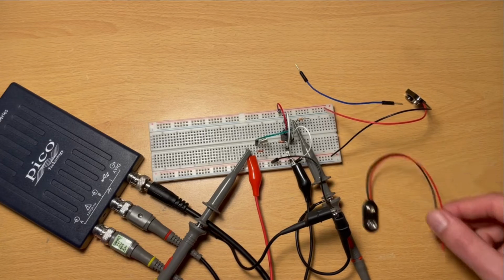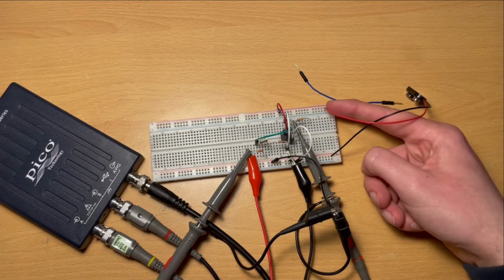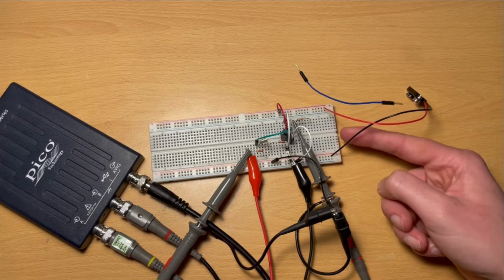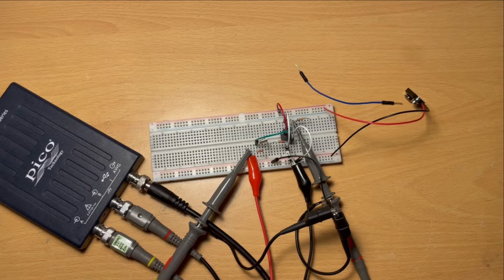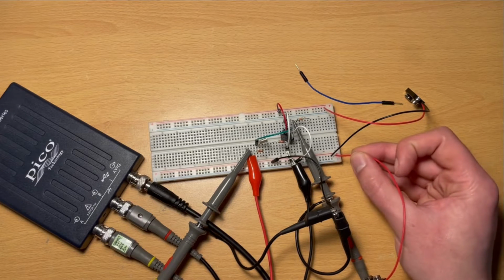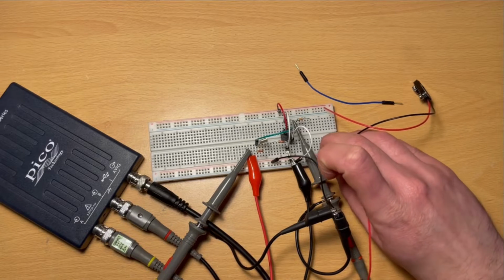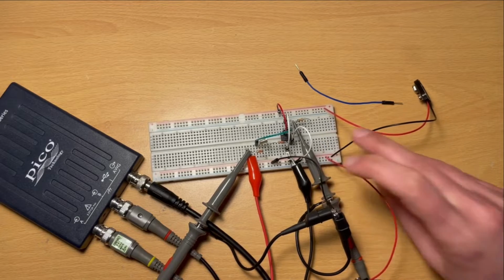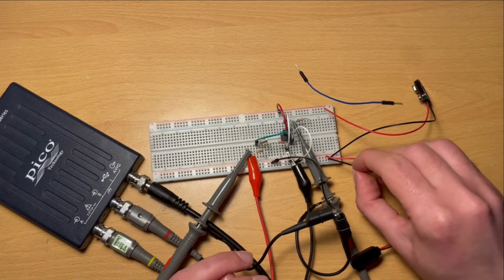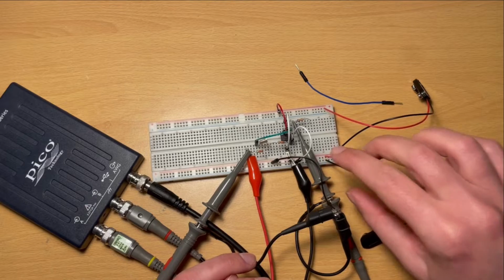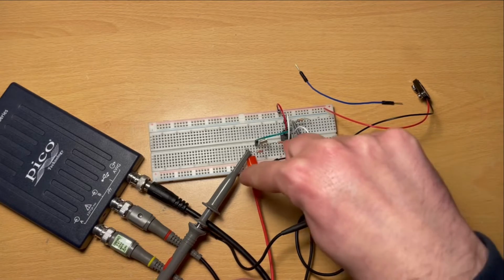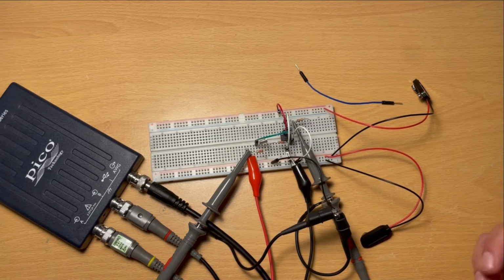So again, recalling the previous video, it's a dual rail power supply, so we have positive to negative on the second, or to 0 on that second last row, and then we have positive in that second last row to negative on the row below, and that's going to give us a -9 volt rail along the bottom. So we have a dual rail supply now, but more information about that in the previous video. I'll connect up some batteries and we'll start up the software.